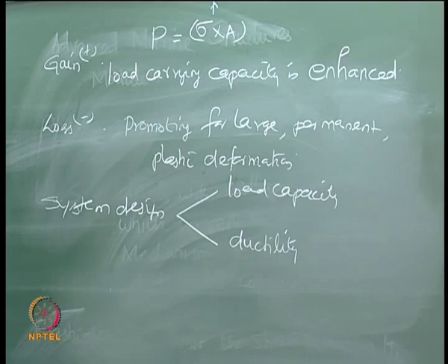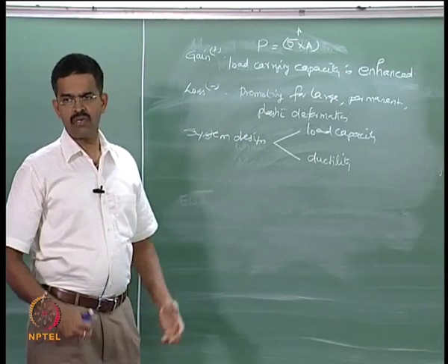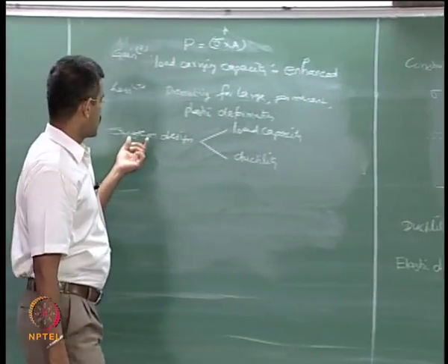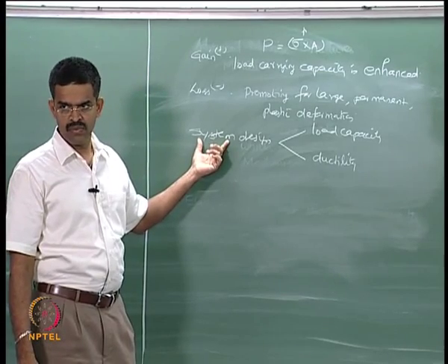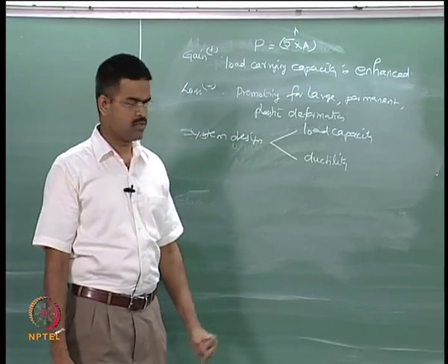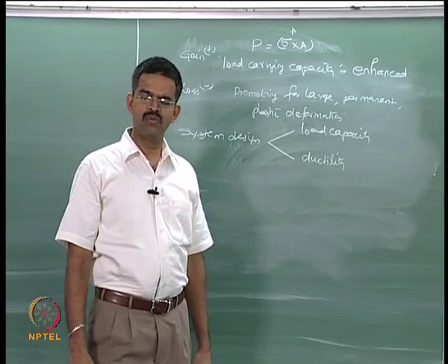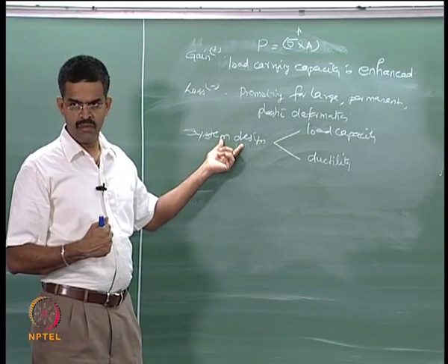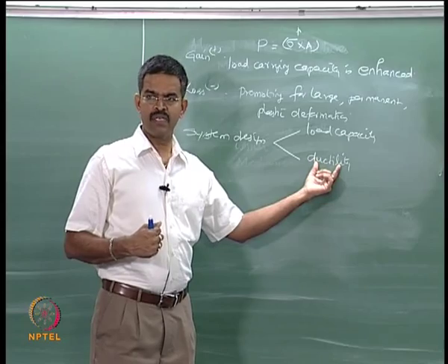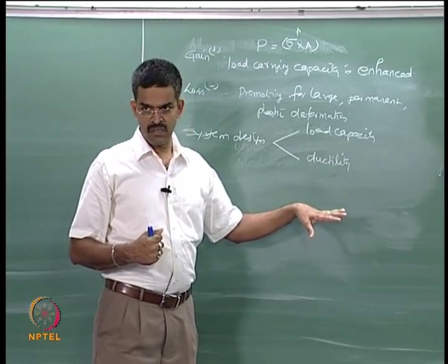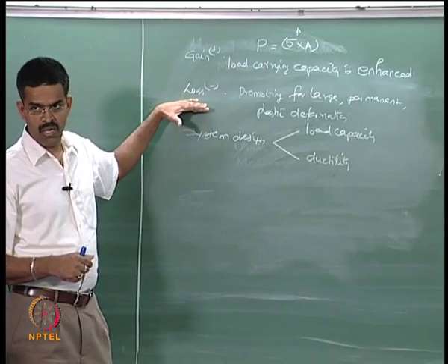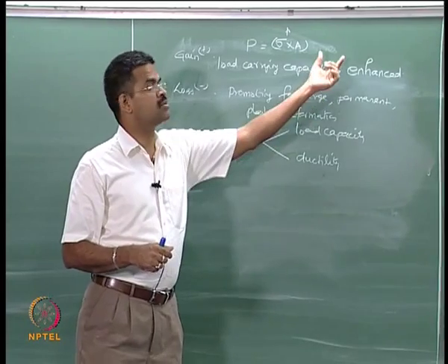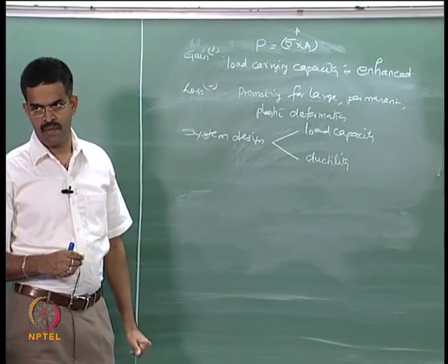Let us say, for example, any brittle material which does not have a very good ratio of ductility, then obviously this concept of design which we are proposing now, to extend beyond the elastic limit or beyond the first yield value, cannot be used, because it implicitly demands a ductility capacity in the material which is utilized, and I will call that a loss, because no structure would like to have a permanent deformation on increment of any load capacity. Okay.